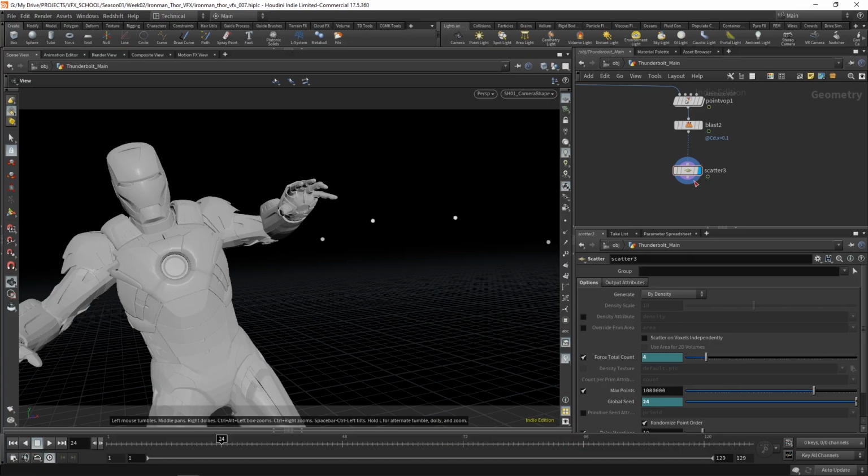The next thing we want to do is we're going to use these points to copy splines onto, and then we're going to apply the same type of distortion to each one of those splines. But we know, as we've seen before, if we want to copy something to points, those points need to have at least a normal.